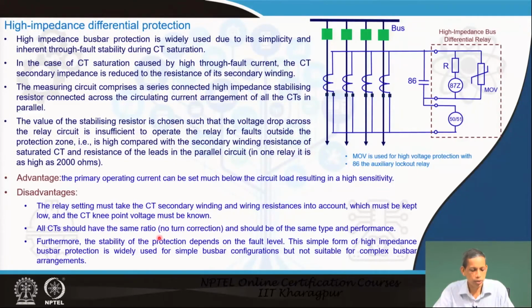All CTs should have the same ratio. This is another typical requirement, and they should also have the same type of performance. Furthermore, the stability of the protection depends on the fault level.